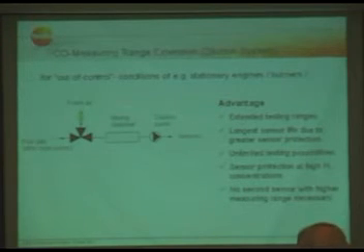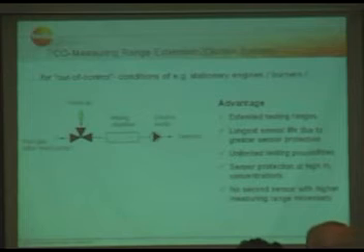And since we know which dilution factor you have chosen, you will get the actual reading. That means 10,000 ppm in the display of the analyzer. The sensor gets only 50 or 100 ppm, but you will get the real CO concentration in your display.